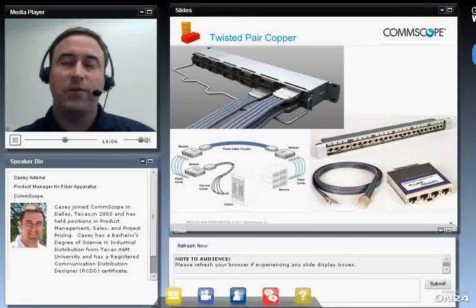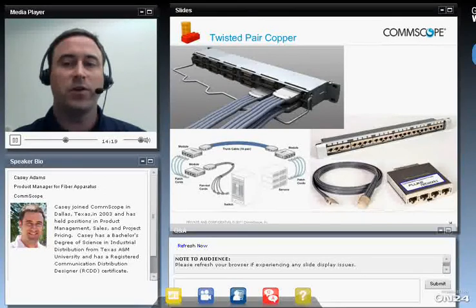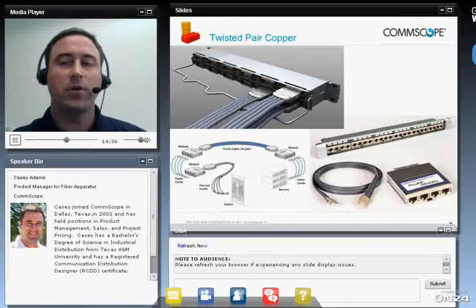even though fiber is seen as the wave of the future, copper will continue to be a significant part of any system. This slide depicts products that are part of the Systemax Instapatch Quattro line. The idea of Quattro is to capitalize on the ease of use of a pre-terminated fiber MPO system and apply that to copper. Using a trunk cable made up of 16 pair copper, you have the opportunity to design a system that has a pre-terminated copper solution that enables less time in the data center for installation. The modularity of the product is based on 4 components.